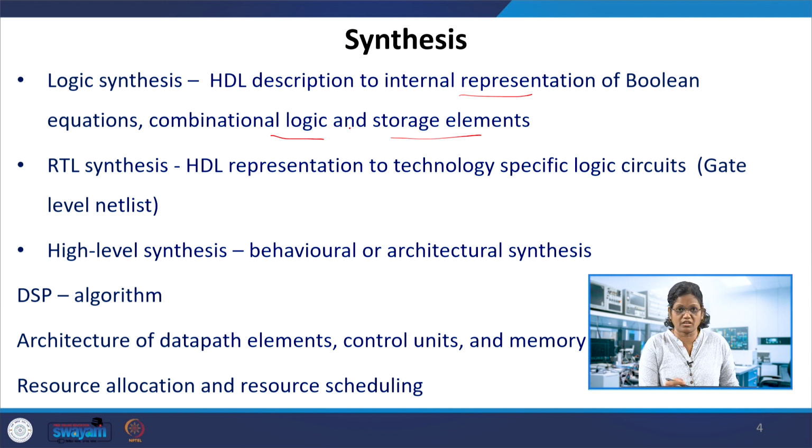What is the logic behind that? Combinational or sequential storage elements are used. So those contents are the outcome of this HDL description in logic synthesis. Whereas in the case of RTL synthesis, we convert this HDL description to technology specific logic circuits, like a gate level netlist. RTL here means register transfer level. So register transfer level synthesis finds out which technology will be used and what is the specific logic circuit for that technology. Based on that, the gate level netlist will be generated.